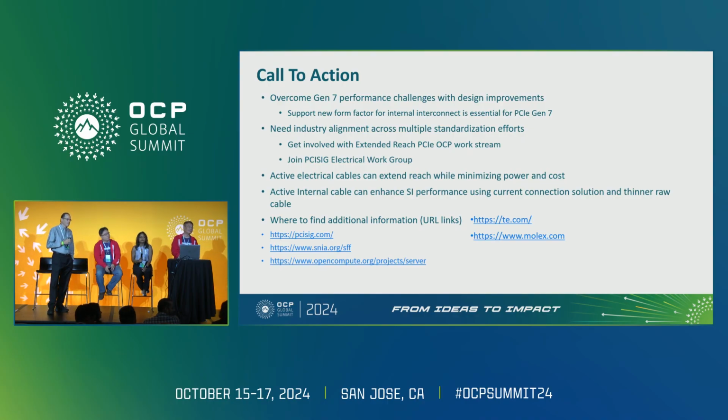So I have a question on the new connector proposal. We're looking at the same thing in Ethernet, but PCIe is extremely cost sensitive. How do you see the feasibility if you go to a two-piece connector? Maybe that doubles the cost. Is that even feasible for PCIe despite the performance benefits? You're talking about the internal cable, the new connector, the new form factor? She's talking about the Gen 7 connector. Yeah, I'm sorry, I forgot the name. That's okay. Yeah, we think we can make it because it's on a schedule for samples in January. It's based on stamped and formed, so it makes it affordable, yep. Thank you.